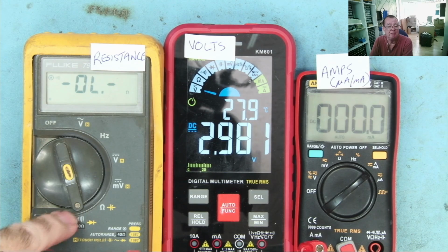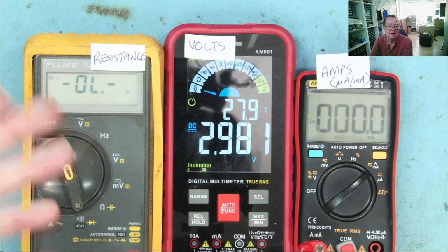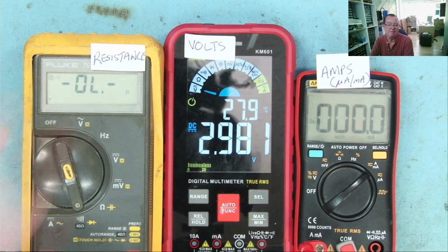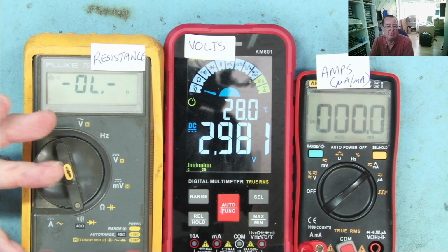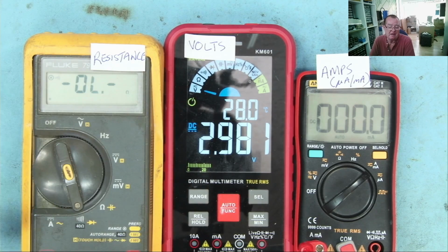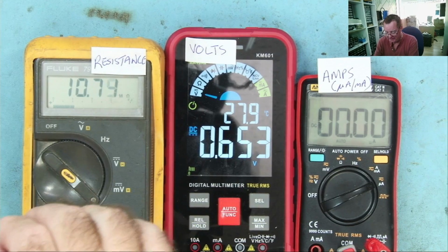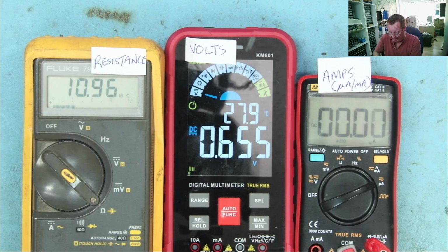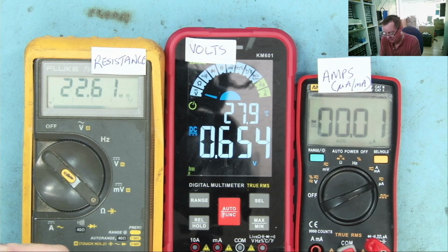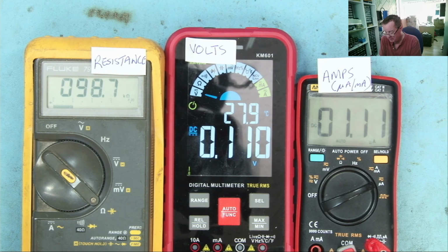So once again, when you're in continuity mode, it can't actually generate the higher voltage because the current would be so high. So for low resistances, fair enough, it is generating the voltage and it knows what it is, but once you get to the higher resistances, you can see it's a constant voltage generator, and that will apply with much higher resistances as well. For example, here is a 100k resistor, and this will still generate about 0.1 of a volt. Let's go, you'll see. Yeah, 0.11 volt. We're back to that again. Constant voltage with 100k.